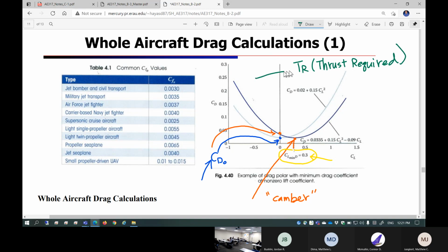So as you design your airplane's aerodynamics and come up with a configuration, you're going to determine thrust required. This is going to be a driving factor of what type of engine you need to choose. Of course, you have to have an engine bigger than this thrust required, otherwise your performance is so poor that sometimes your airplane cannot even fly.